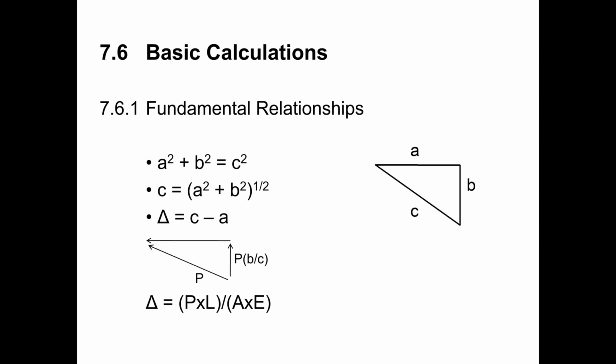All right. The other thing that we're going to calculate in Chapter 7 is we know that when we tension the strand in the straight position and then we push it down or pull it up into the draped position, that we're elongating the strand and we're adding force to the strand, we need to be able to calculate how much force is being added to the strand so that we can accurately determine what our jacking force should be.